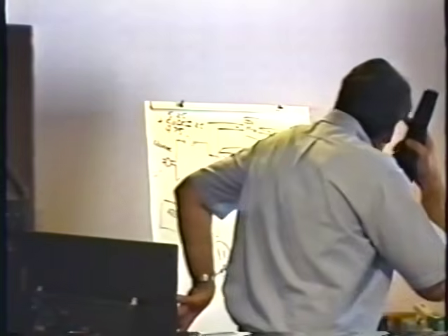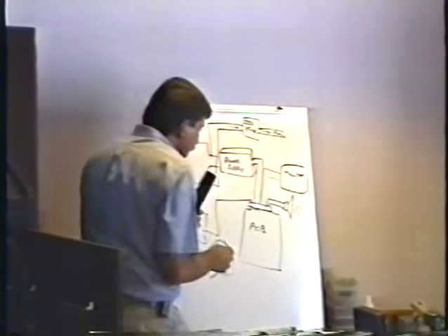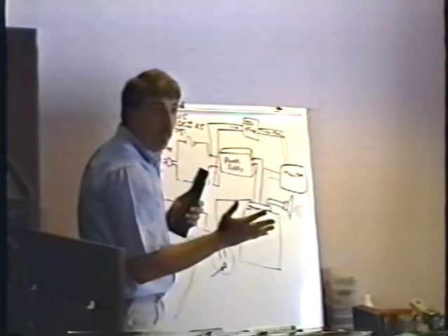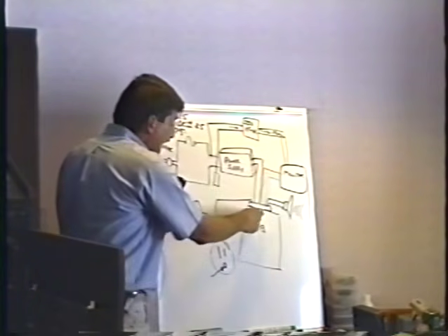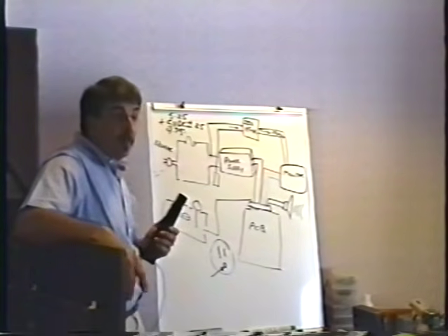So that's a good place to check the 5-volt power supply, because that way we're checking it on the board. And I adjust it so that it's exactly 5.1 volts on the board, and then I know that I've got my proper voltage.